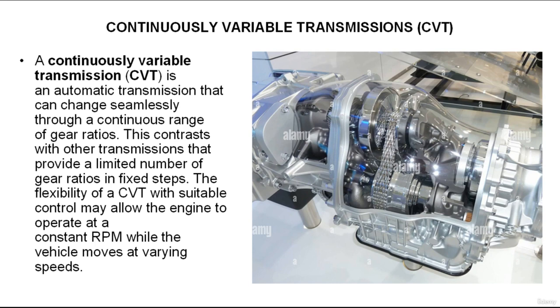Another unconventional transmission design, the continuously variable transmission, CVT, is a transmission with no fixed forward speeds. The gear ratio varies with engine speeds and temperature. These transmissions are, however, fitted with a 1-speed reverse gear. Some CVT transaxles do not have a torque converter. Rather, they use a manual transmission type flywheel with a start clutch instead of relying on planetary or helical gear sets to provide drive ratios.